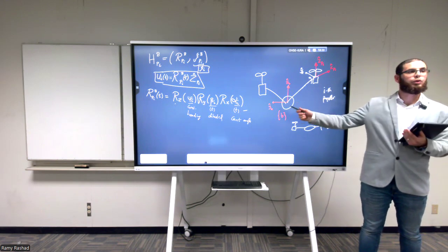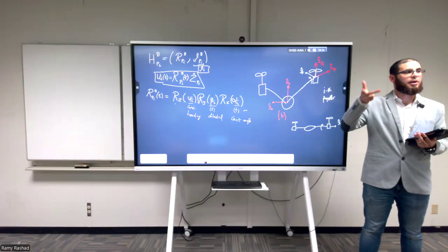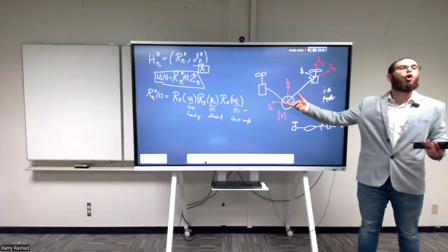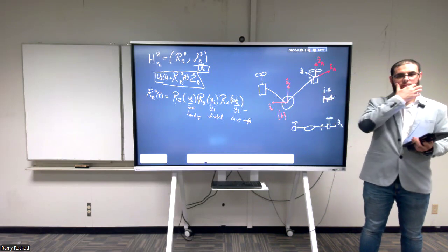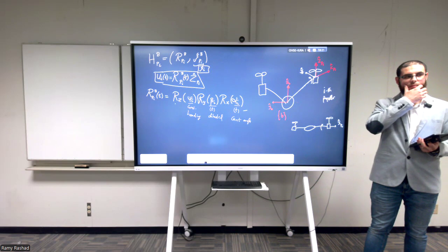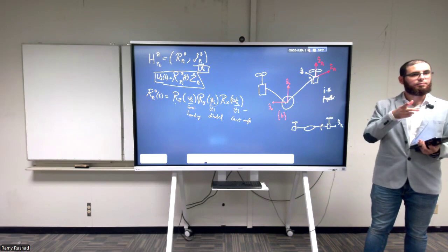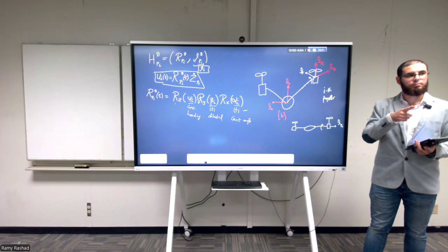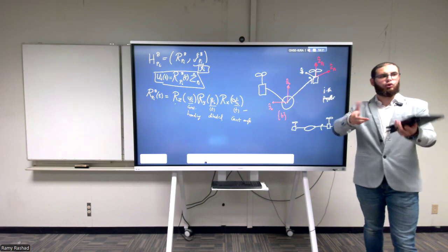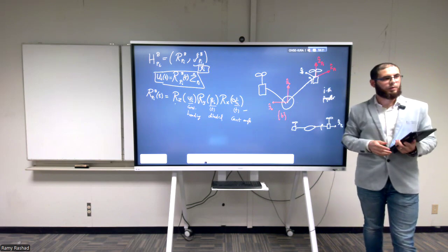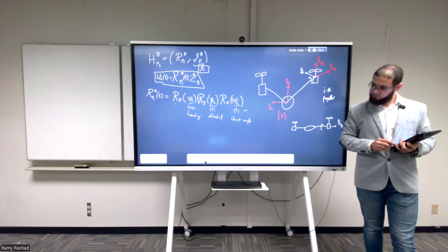This is the first time we chose to represent the rotation matrix by 3 consecutive rotations, or by Euler angles. Okay. You remember I always told you don't do that. Why are we doing it here? Because the rotation is limited. We don't need the full 360 degrees to rotate the drone. Maybe that's okay. We only need some angles. That's okay. There are some singularities. Okay, good point.